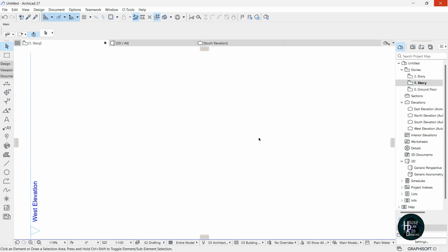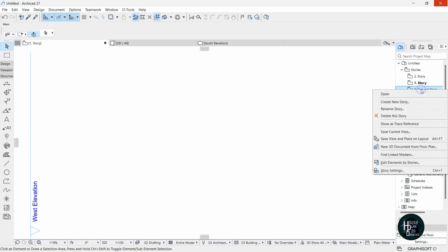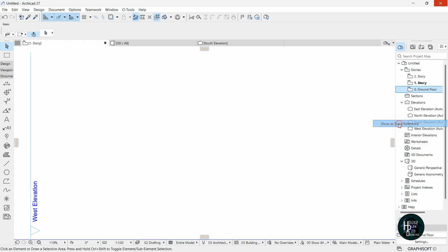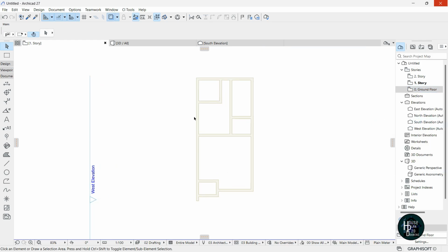So for us to go about that, what we want to do right now is, while I'm still on the first story, I'm going to right click on the ground floor and I'm going to select this show as trace reference. Okay, click on it, and now I'm going to be seeing what I have on the ground floor. I can't select anything here. As you can see, I can't select anything whatsoever on this place. Everything here is just the way it is. Okay, so now we're going to start drawing the first story.